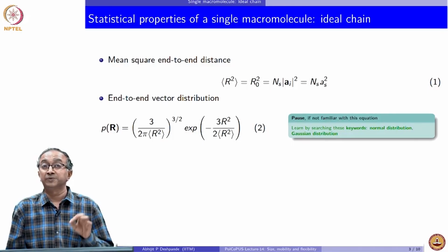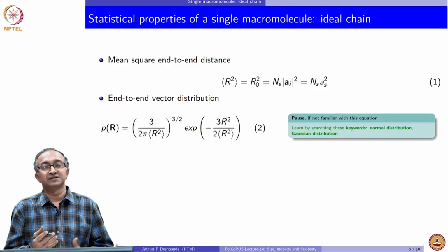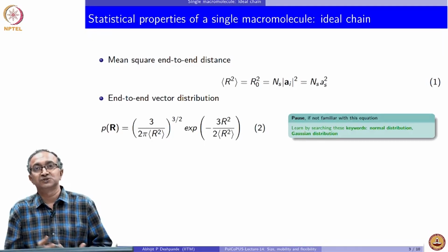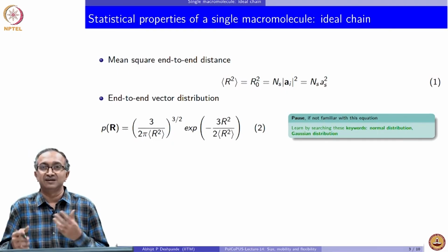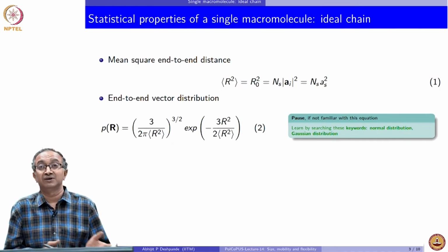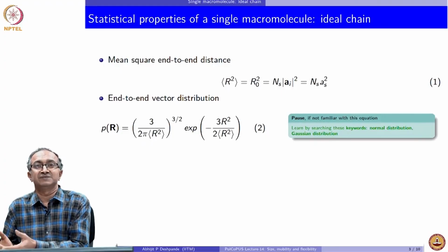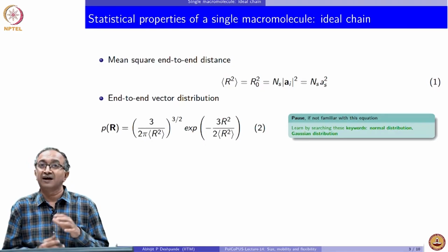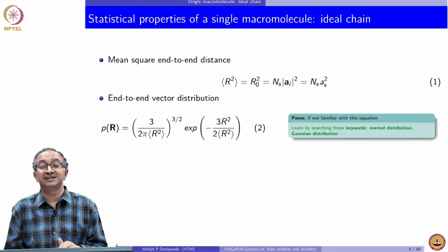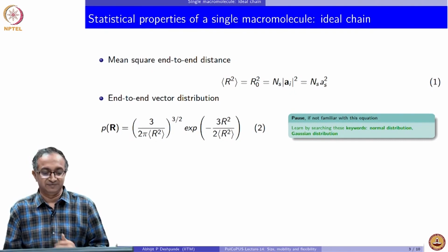But even to obtain amorphous or crystalline state, quite often we may be having the polymer in a liquid form and eventually going to the solid form. So what happens to conformations in the liquid state has a bearing on what is the kind of solid state we get in the end. So therefore, conformational changes and single macromolecular behavior is very important even for deciding what solid state we get.